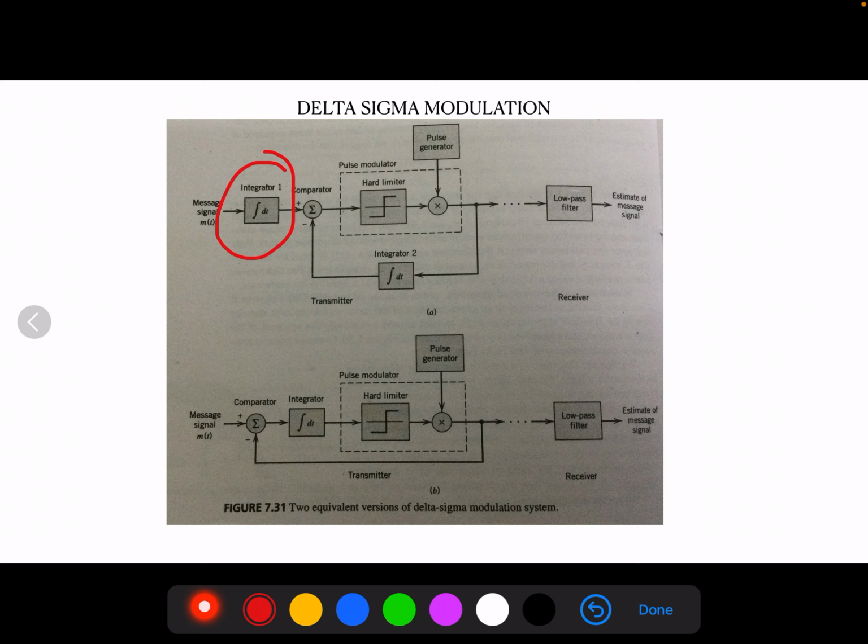with the following beneficial effects. The first thing is the low frequency content of the input signal is pre-emphasized. Second, correlation between adjacent samples of delta modulator input is increased, which tends to improve overall performance by reducing the variance of the error signal at the quantizer input. Design of the receiver is also simplified.